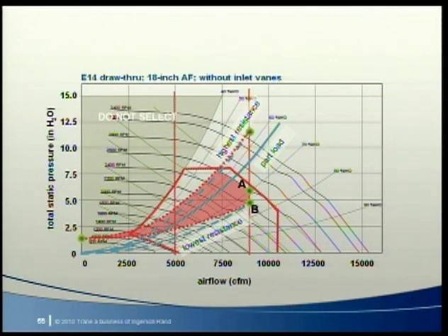If airflow drops to 5,000 CFM, we need to verify that the new fan speed is still within the selection envelope. The fan speed depends on sensor location, pressure set point, and the current system curve. With the sensor located near Zone 1 and set to maintain the duct at 1.3 inches above outdoor pressure, the fan operates somewhere within the shaded area shown.